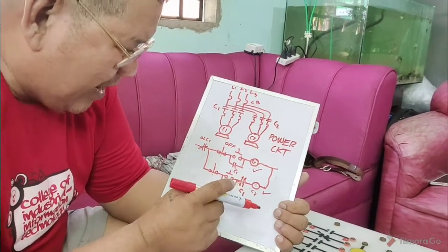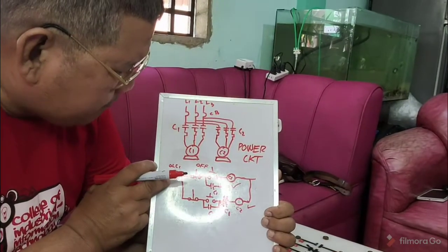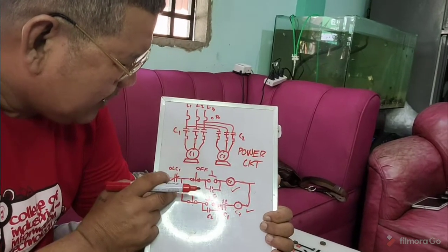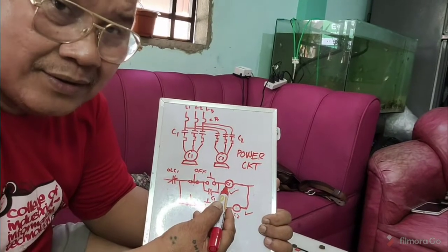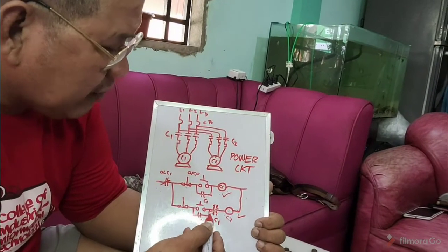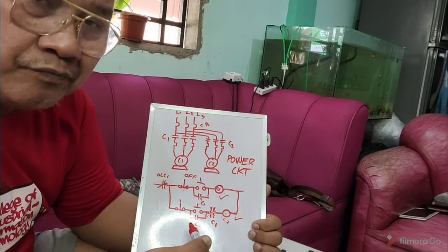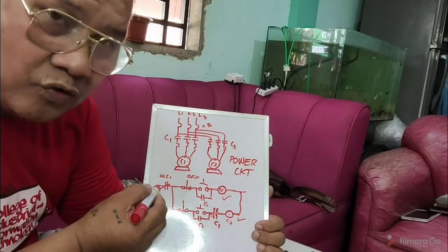So that is it. Now, remember, I put only overload contact 1 here, right? This overload contact 1 is only intended for conveyor number 1. What if there is trouble or overload in conveyor number 2? There is no protection here in the absence of an overload contact.